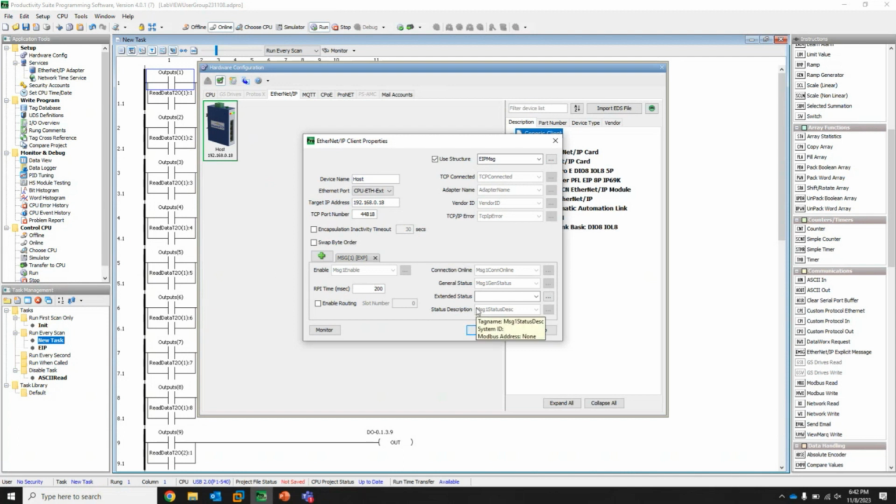Doing this on a Rockwell PLC is very similar. You go down in your tree. I don't have Studio on this computer. But I know as you go down in the tree, you can drag in a new EtherNet/IP generic, and you can do basically the same thing. It's a different looking dialog, but you would specify that it's explicit messaging. You would specify the instance IDs and the size of data and how often you want that data exchange. And then you simply map that to its tags and you're good to go.